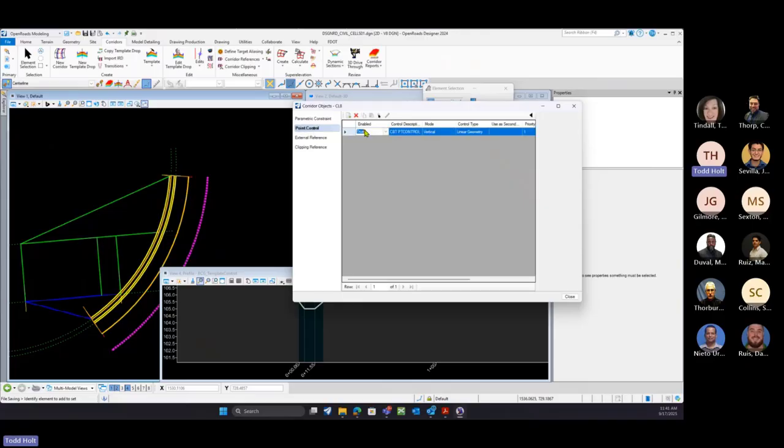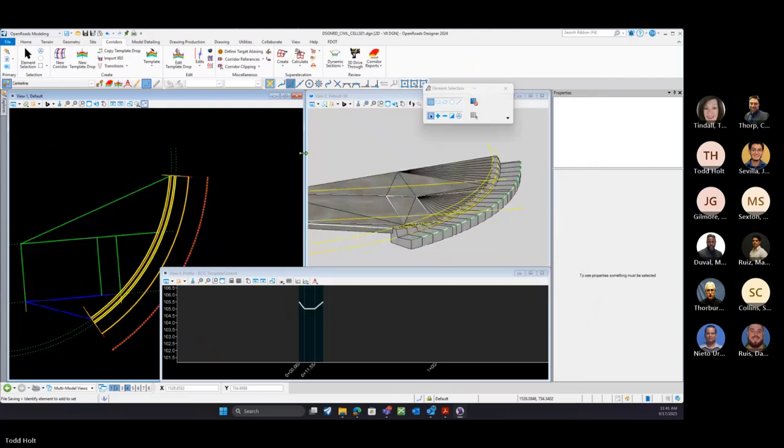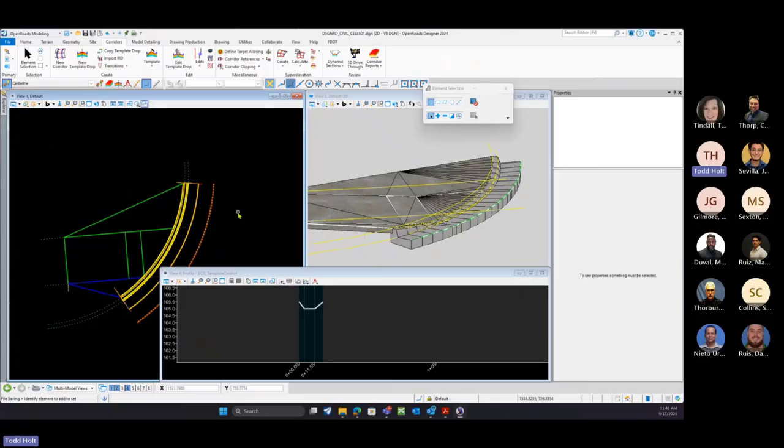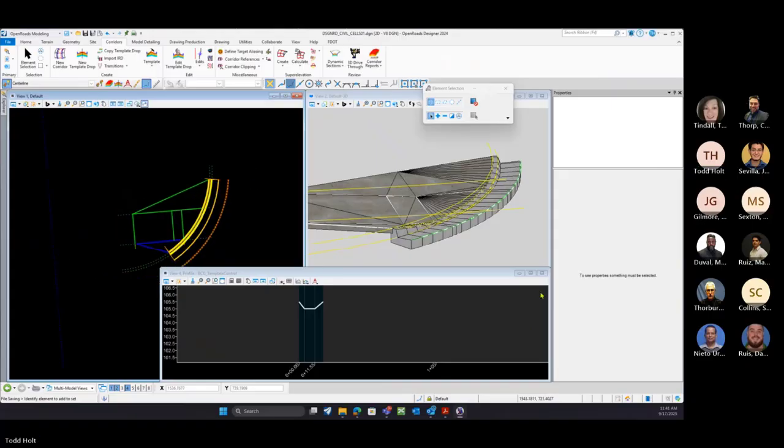But the point control, that's going to be locked to that control. You control it horizontally, vertically, or both in that geometry. That'll hold up better in the civil cell, in both linear templates and corridor templates. So at this point, you could just reestablish that and place it again, and then you could pick that edge of pavement line within there.